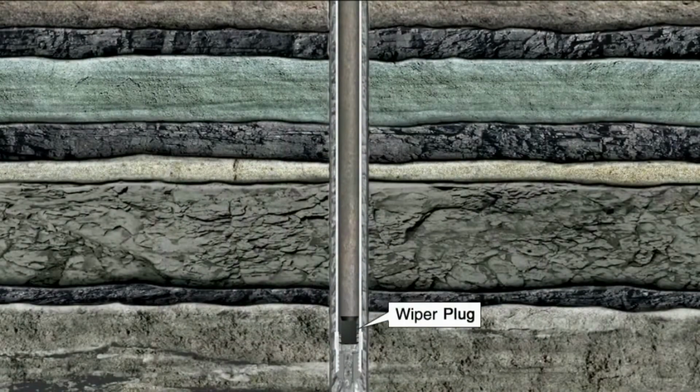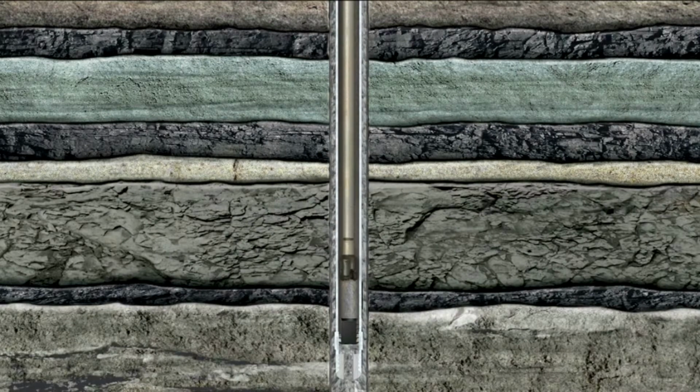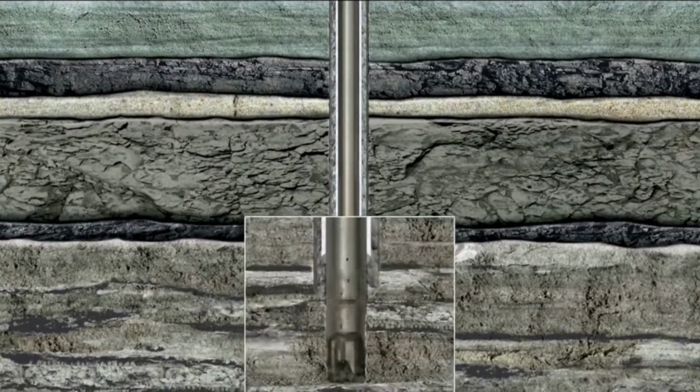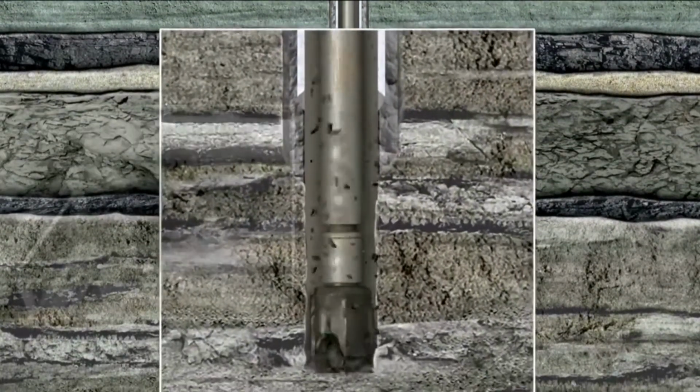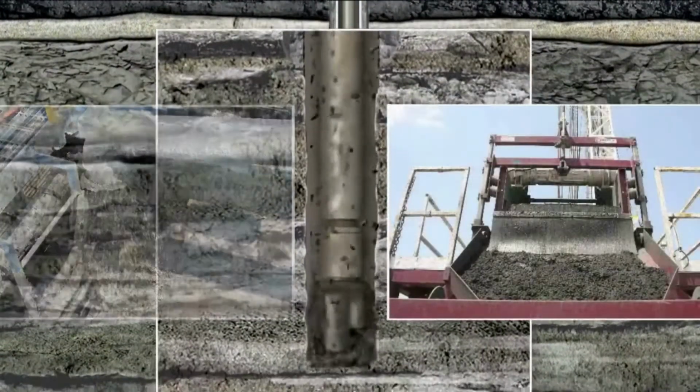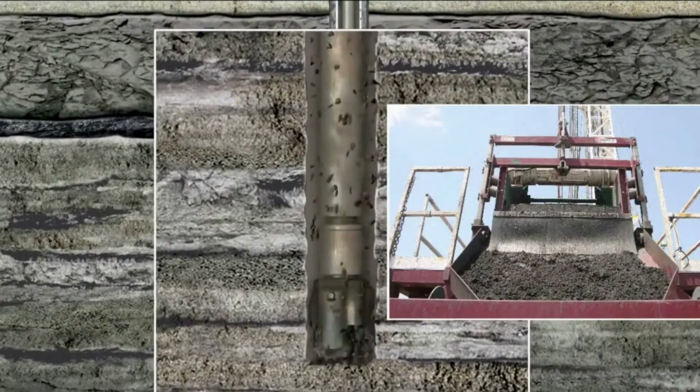Once the casing cement has set, drilling of the next section of the hole continues by drilling through the wiper plug, shoe and cement at the bottom of the well bore and on towards the lower target zones. Throughout the drilling, a mixture called mud is pumped down into the well through the drill pipe. This serves to keep the drill bit cool. It not only carries the cuttings to the surface, but it provides hydrostatic pressure, preventing any formation fluids from entering the well bore.